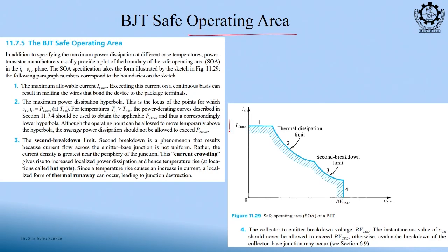So, we know that for a power amplifier my current will be high, right. So, most of the power amplifiers operate at the output stage, and we have seen that it goes to full swing, right, VCC to minus V, twice V, its swing is twice V. Now, this transistor has some rating, a particular rating, and we should choose the highest rating. So, the breakdown voltage is also specified.